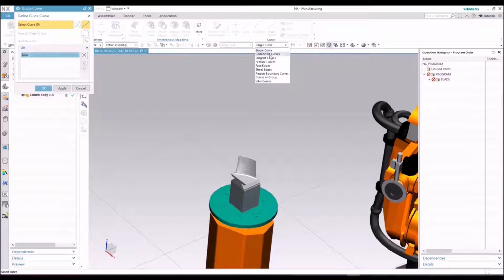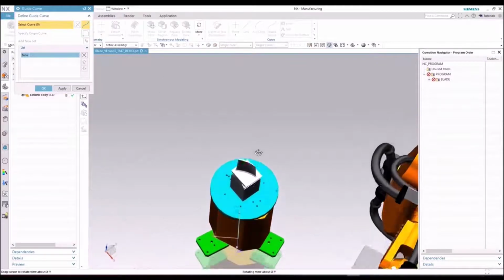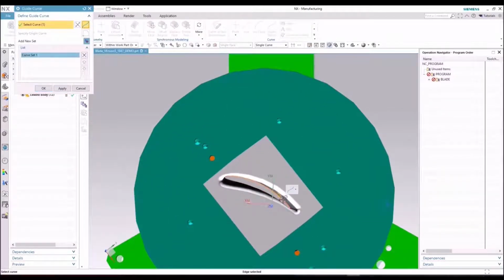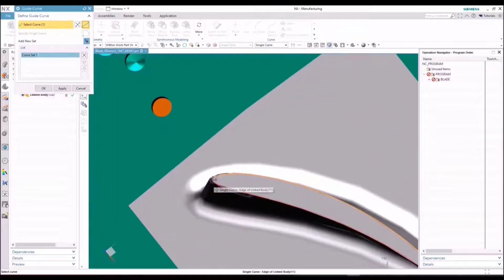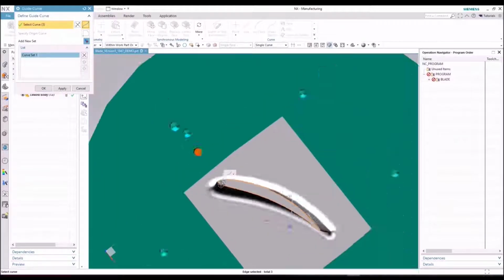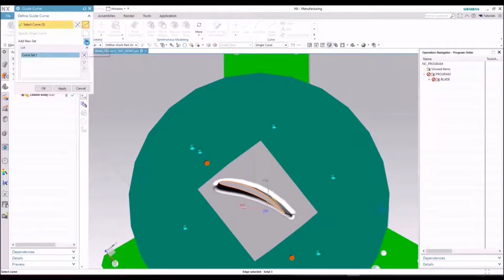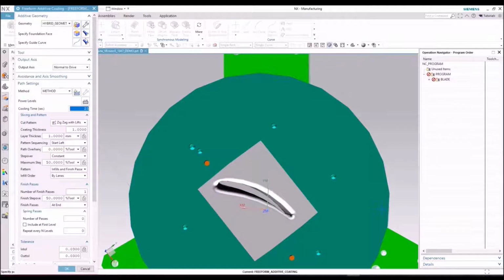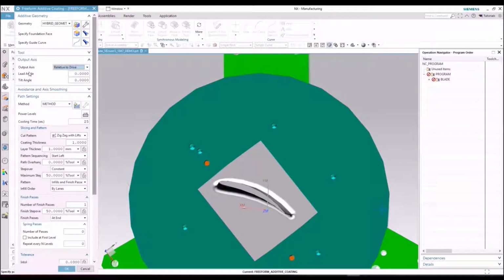Moreover, curve manifolds can be defined. Again, attention needs to be paid to select the appropriate curve orientation. Beyond the tangential traversing speed, the cold spray process typically requires full control of the accompanying tripod along the entire tool path. NX-CAM allows for separate specification of local lead and tilt angles with respect to the local surface normal. These angles can be set in the multi-axis deposition module and the freeform additive coating section.